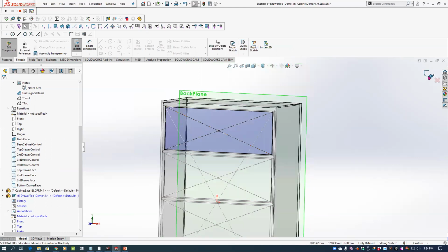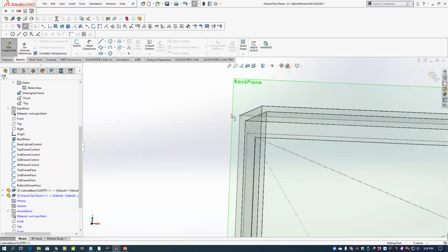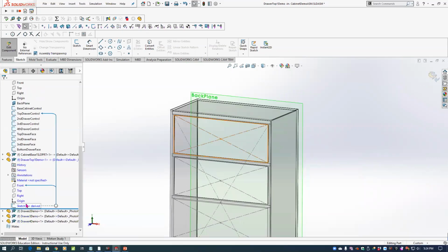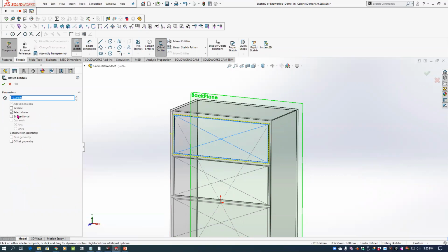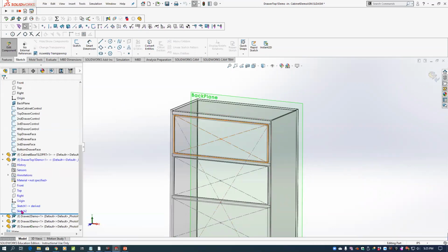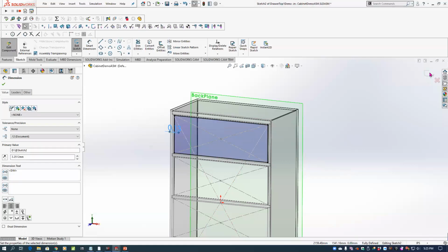And rather than using that directly, let's offset that because we've cut with that same profile. Let's use that sketch to just do an offset, so we've got a little bit of a clearance there. So on the front, I'll sketch and then grab that derived sketch and create an offset on the inside. Again, let's change the units on this part as well. And let's change that offset to maybe 1/8 of an inch, 1/8 inch clearance all the way around.